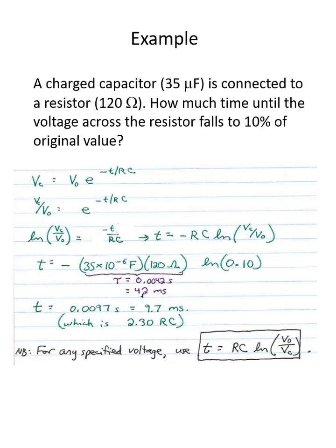The time constant for an RC circuit is a useful measure. It gives you a ballpark figure of what kind of timing is going to be occurring with this RC circuit. Meaning, are we talking about microseconds, milliseconds? Are we talking about seconds? What roughly is the amount of time we can expect? So the time constant, RC, is 4.2 milliseconds. So pretty much any question we're going to ask about this RC circuit about timing is going to be in the range of milliseconds.